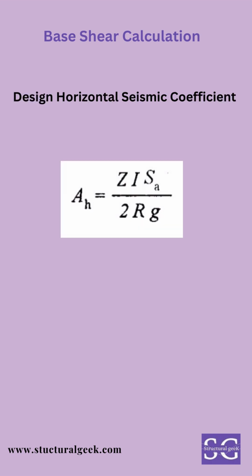Ah, which is the design horizontal seismic coefficient, is given as Z by 2 times I by R times Sa by g. Z is the zone factor, I is the importance factor, R is the response reduction factor, Sa by g is the acceleration coefficient that we have. Now let's see what all these parameters are dependent upon.